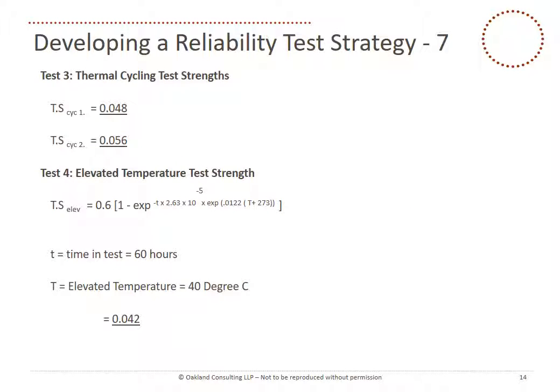Now when we go back to those equations of the 6 and 8 thermal cycles, both the same temperature change rate but different upper and lower temperatures, we see it's pretty small. So we see basically they're both averaging around about 5%. So not too high. So 5% means really there's only a 1 in 20 chance of stimulating a latent defect with that thermal cycling.